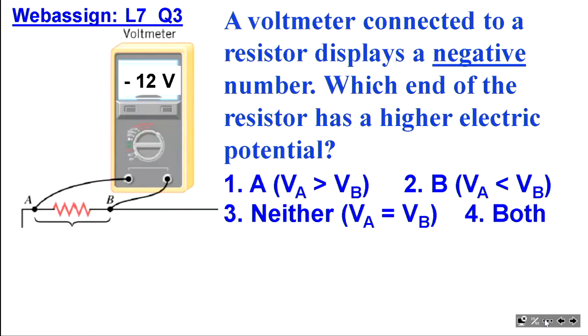Question. So I have to break the circuit again. I don't need to measure electric current anymore. Turn it off, move it away. You are measuring voltage using your multimeter, and the number you read is negative. Does it make any sense? Or if it does make sense, what does it mean? That's the question.